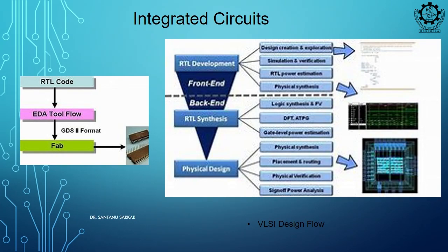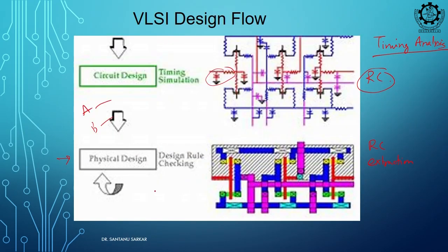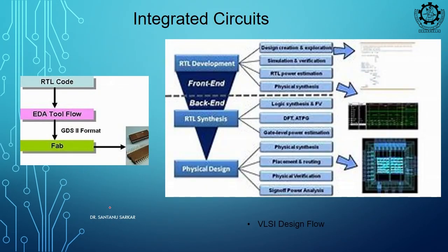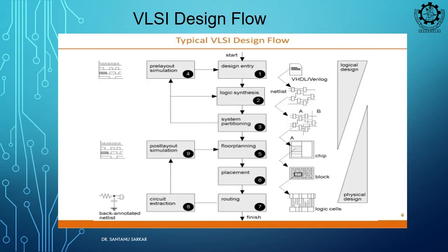Okay. Then after the post layout simulation, you may need to edit your design. Suppose your frequency criteria is very stringent and your layout is poor, then you may have to go 1 or 2 more steps to edit the layout if your frequency is degraded after the post layout simulation, considering all the RC extraction. So, this is your front end and this is your back end. That we just discussed. So, this is our typical VLSI design flow.